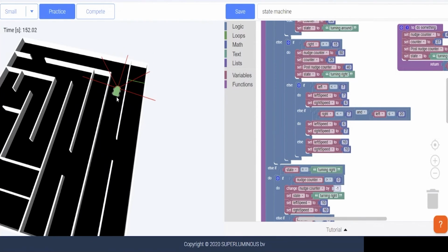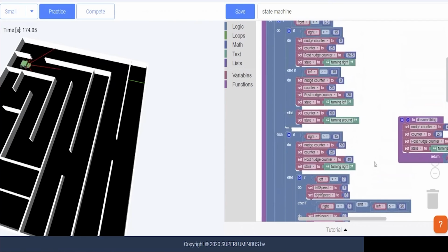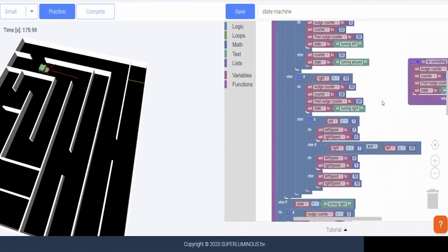So all I've written here is an extra line that basically says, if your right sensor is high and is low, and your left sensor is less than 20. So if you're too close to the right wall, and your left sensor isn't really, really high, there's not a gap there that we're just missing, then you can turn. Then you can speed out of that. Otherwise, just go forwards, right? And this is all of Rupert. This gets you around the maze, okay?